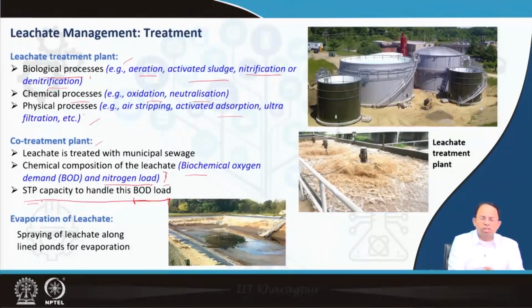So when we design the sewage treatment plant, in addition to designing it for the normal urban sewage, we also have to consider the extra nitrogen load and the biochemical oxygen load, which has to be taken care of because of the incoming leachate as well.